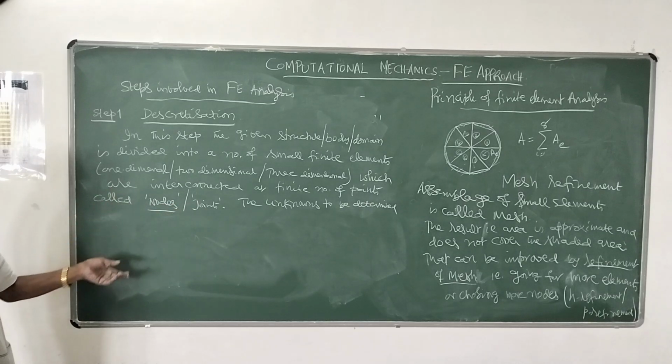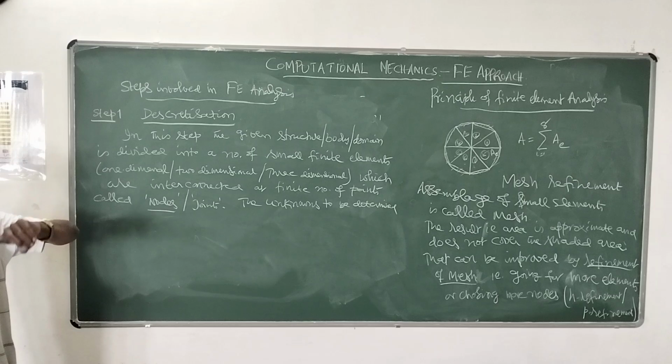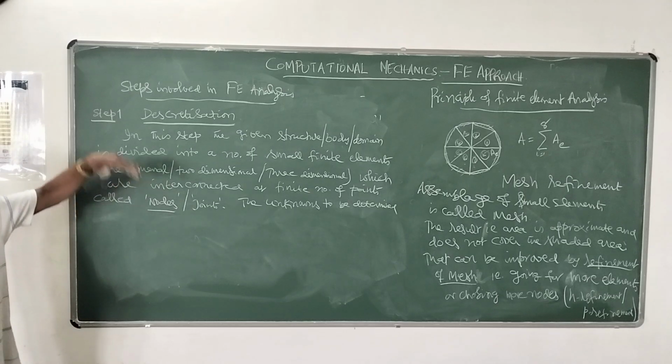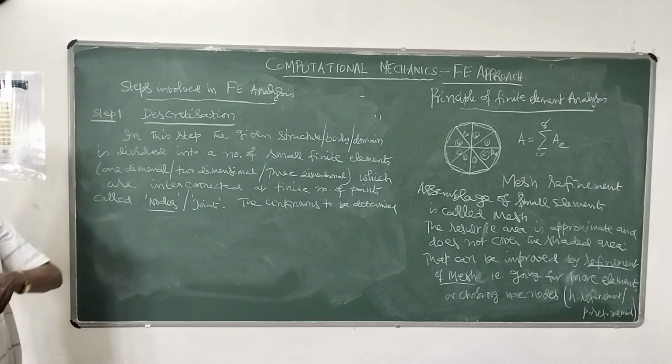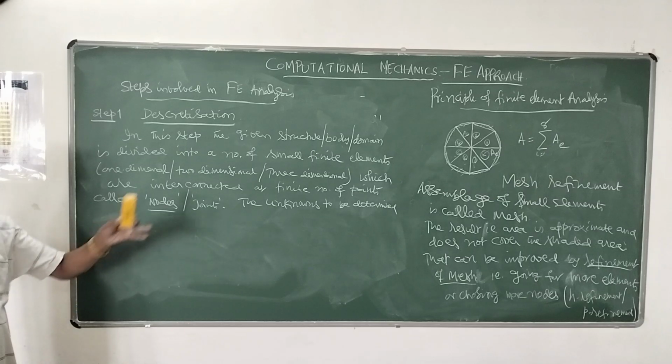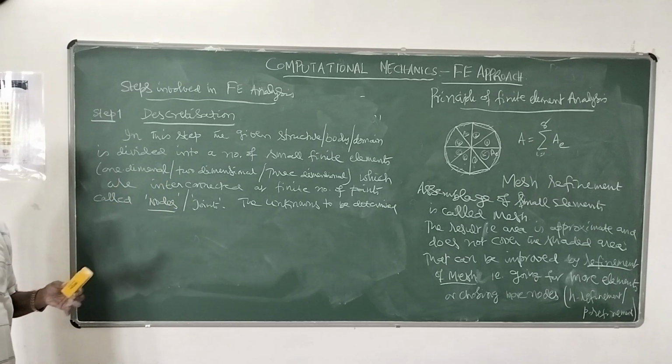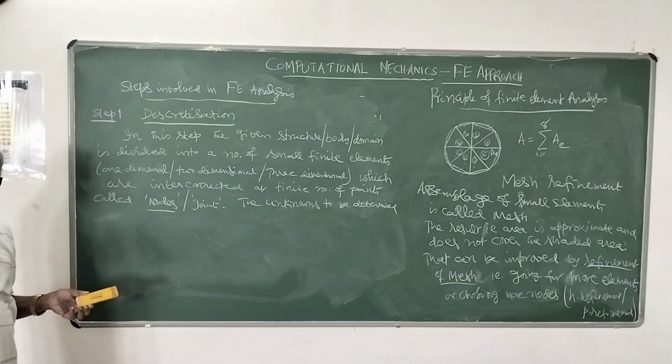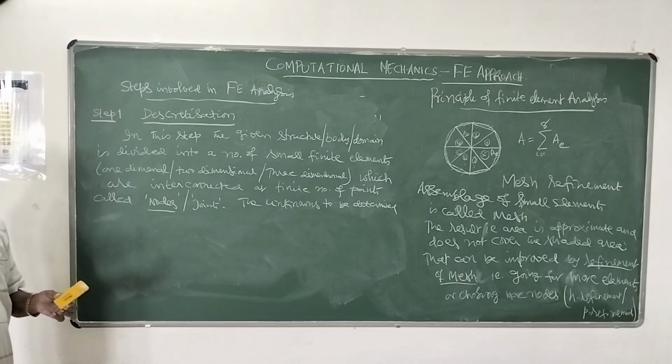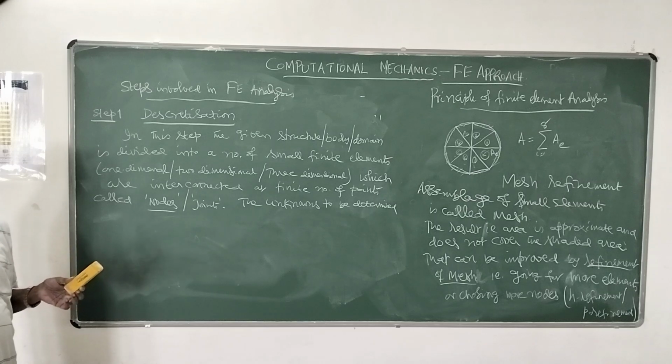That's all. 2 types of deformation, angular deformation or linear deformation. Those unknown deformations you have to determine in global coordinates only, because loads are all in global coordinates. Of course, the loads will be in any direction, but for analysis purposes, we resolve all those loads along three fundamental orthogonal global coordinate directions, x, y, z.